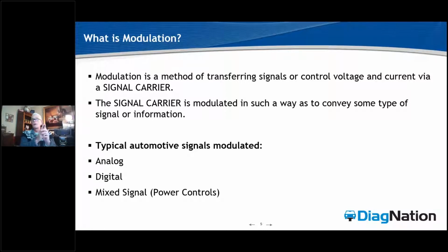So we've got a short pulse period for the low setting and a full-on high pulse period for the high setting, where it's nuking your backside as you drive down the road, right? So there we have a digital or mixed signal coming out to us in our scopes and our meters and our scanners in the analog realm, right? Very important distinction when looking at pulse width modulation.